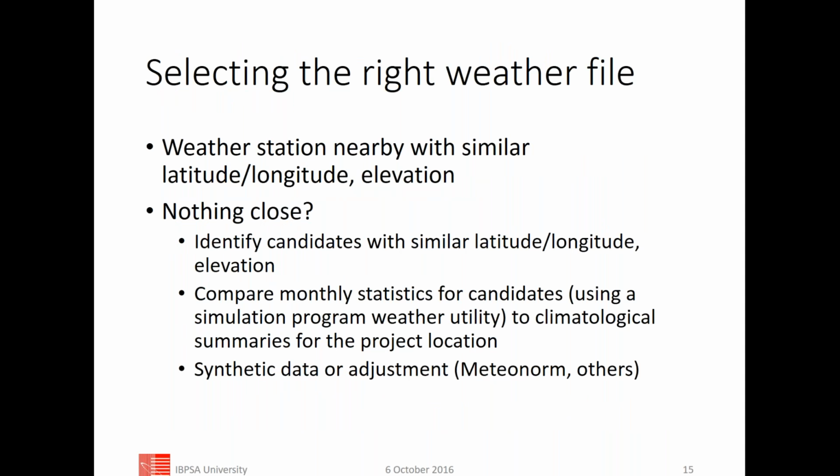So, selecting the right weather file. If you're lucky, you happen to be in a large urban area or near enough by, and there's likely to be an airport, at least if you're in North America or Europe. In other locations, you may have to try to find something that's maybe not within 100 kilometers or so, but it matches climatically what you're doing.